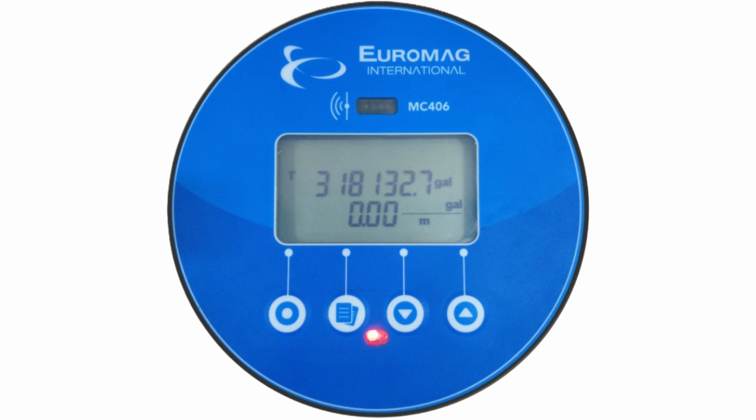When looking at the display, notice there are two lines of data. The upper row is showing the totalized flow, while the lower row is showing real-time flow. It is important to notice the T on the left side of the upper row of data. This T represents the total net forward flow since the meter was first installed.